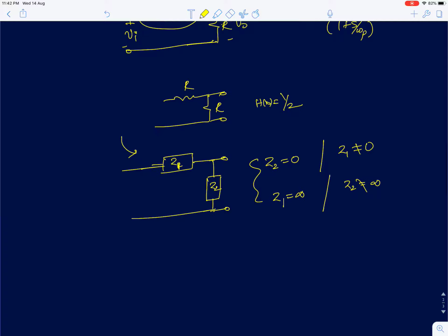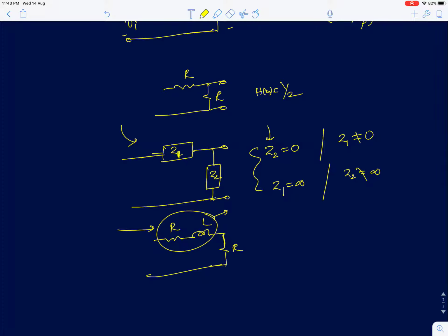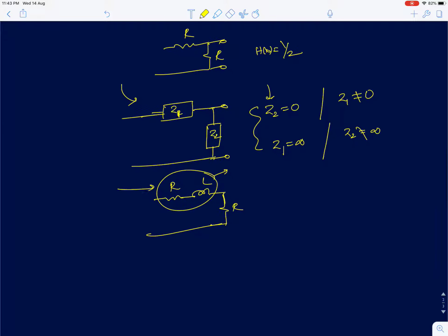So using that, I am going to first start with the circuit which we had already analyzed. Now if you look at this, for you to get a 0, this impedance should go to 0, but that's a resistor, so it will never go to 0. So that condition is ruled out. The other possibility is this impedance blowing up to infinity, and that will happen only at omega equal to infinity, when omega L becomes infinity. Inductor will have a very high impedance, so that tells us the 0 is at infinite frequencies, which means there is no 0 in the circuit at any finite frequency.